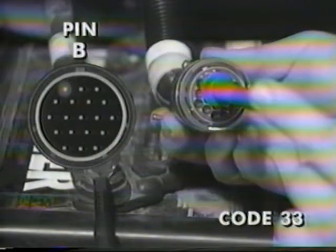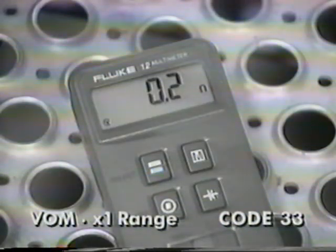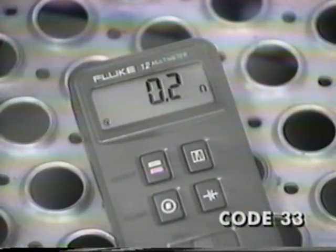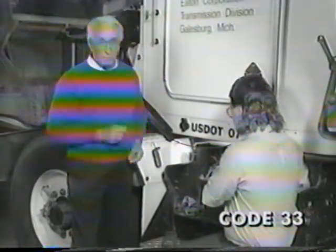Our reading was okay, so next, measure the grounds. Turn the key off and measure the resistance between pin B and the negative battery terminal. Don't clip the black lead to the chassis for this test. You need to go right to the negative battery terminal. Resistance should be less than 0.3 ohms. This one is okay. Do the same thing with pin C. Once again, the resistance should be 0.3 or less. If you find problems during this test, see the troubleshooting guide for help.